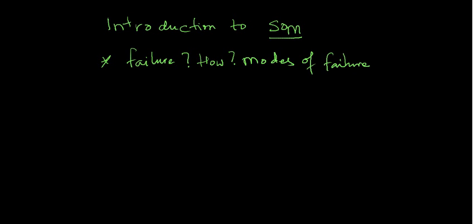when we are talking about loading of different members in a structure, then we talk about how actually this member is loaded. So if we look at the very elementary studies of strength of materials, we will see that members are subjected to basically three kinds of loading. So the first kind of loading that a member is subjected to is an axial load. The axial load, as the name suggests, acts along the axis of the member.